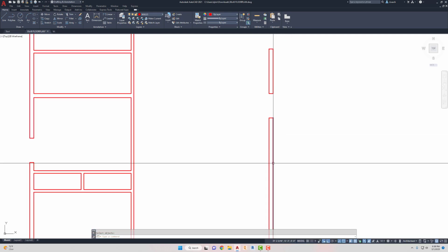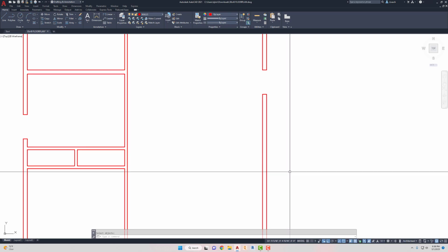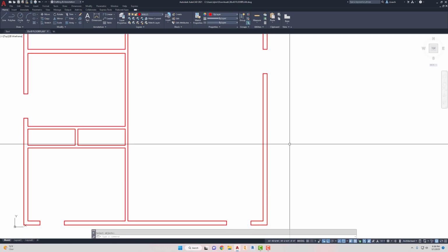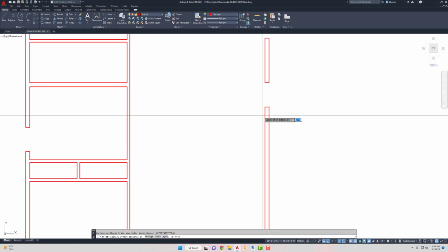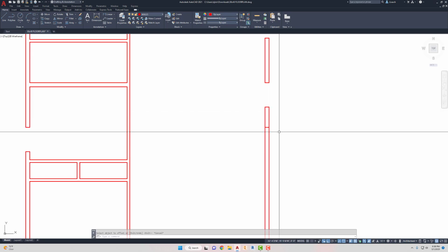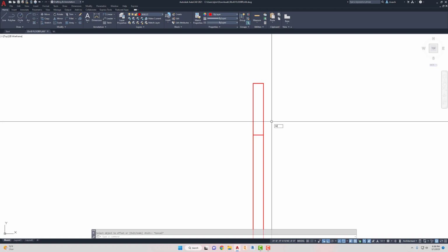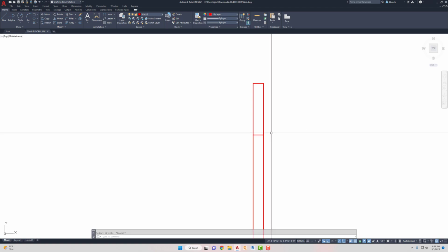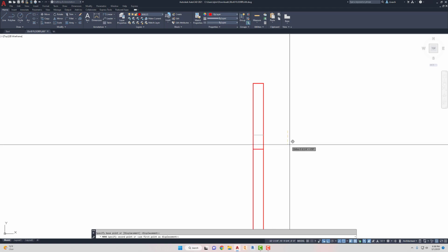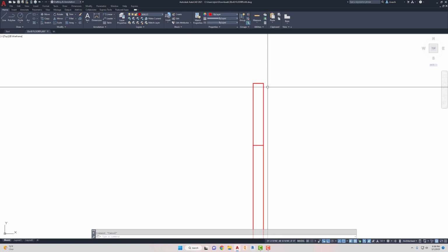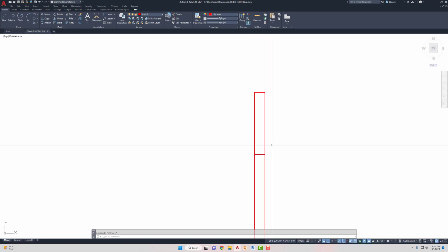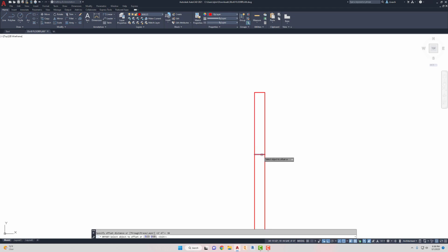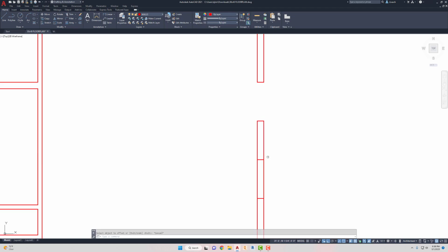There's going to be our entry door here. And then on the other side is another window. So I'm going to say that let's go another offset 30 here down. Actually, let's move that 6 inches down. So I got 36 inches from the end of the window to the end of this door. I'm going to offset this 36 for our door opening. Trim that out.